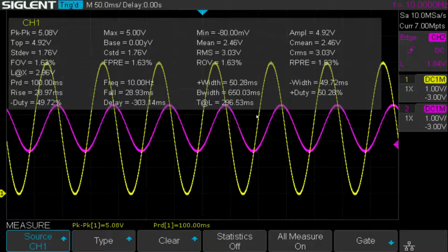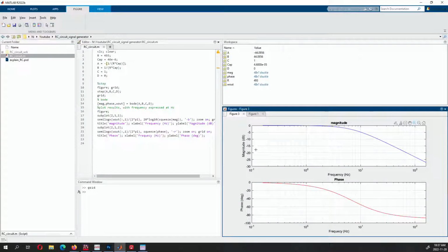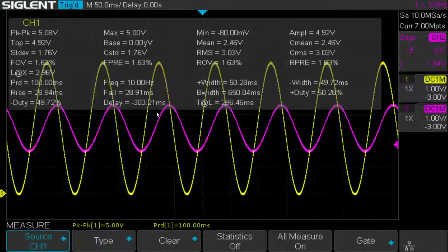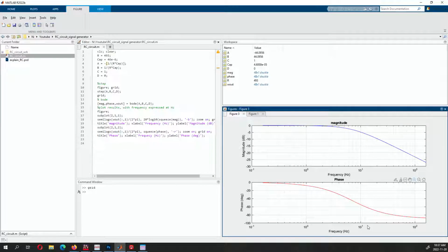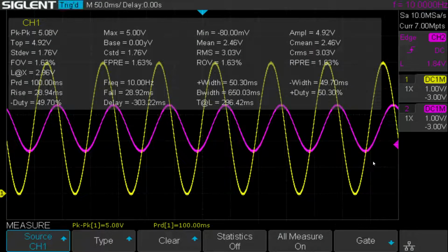And you don't have to do this at every frequency. This is what the Bode plot does, is basically giving you a spectrum of the frequency response, and that's why it's such an important tool to use, because you may not have the instrument to go all the way to thousands of hertz, maybe even a gigahertz, but this mathematical analysis is already giving you the spectrum. It's basically saying from very small to very high, this is how it should behave, and from here you can actually see that. So I can keep increasing it to 10 hertz, and then we'll go to 100 hertz.